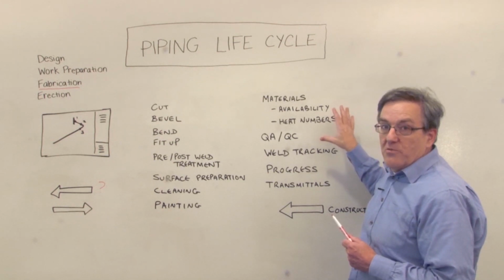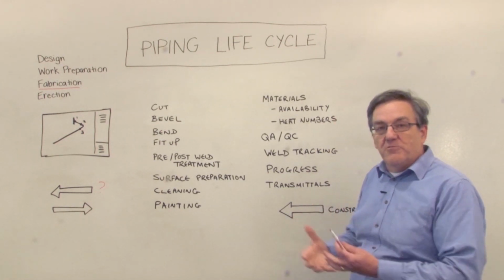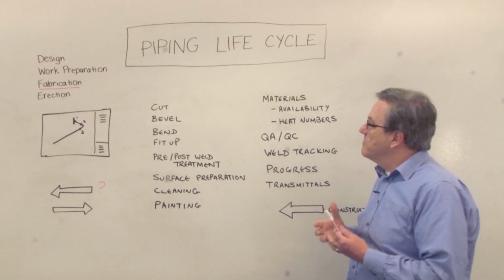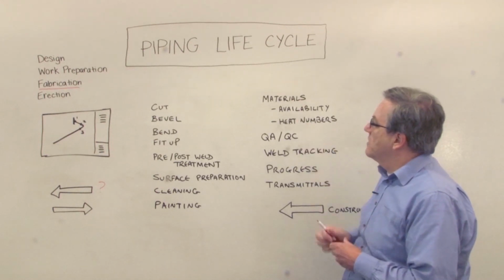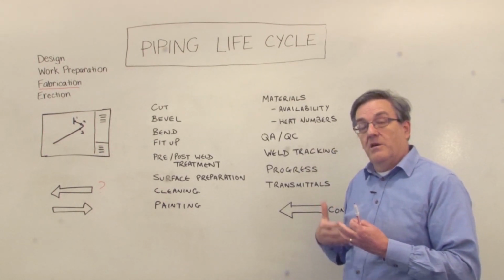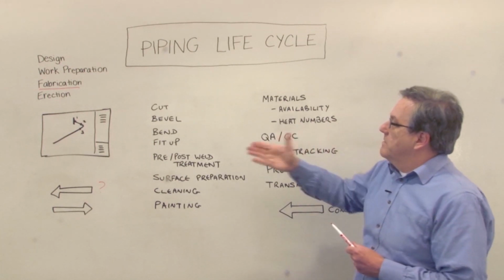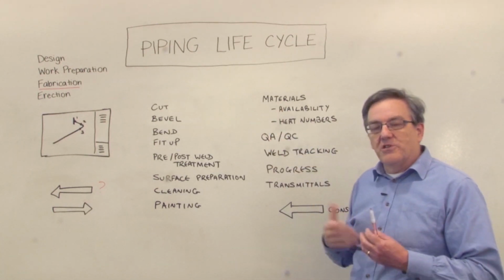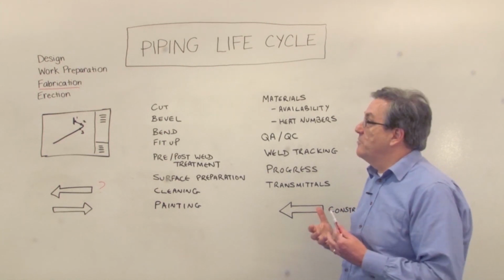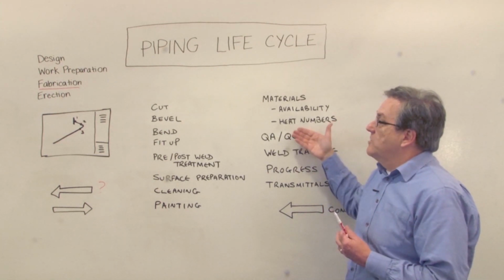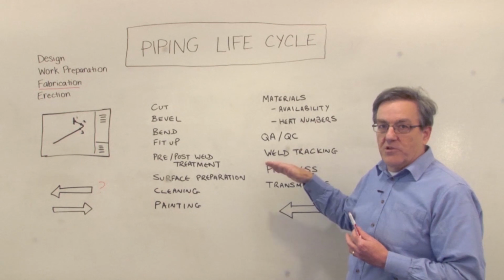Once we actually physically weld, we need to record things like heat numbers and material certificates for the particular pipe, and this is all about being auditable and traceable. We need to test, so the number of welds and the type of test we need to do has been determined for us, but we actually have to carry out those tests and record the result.